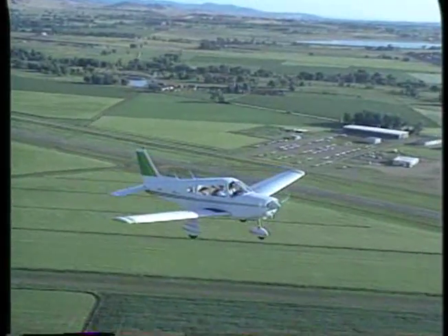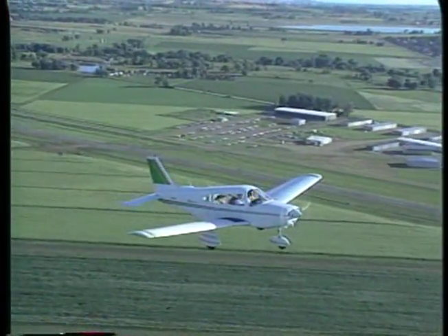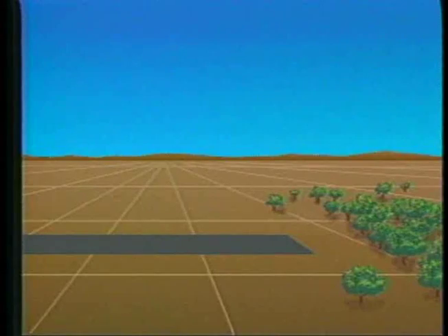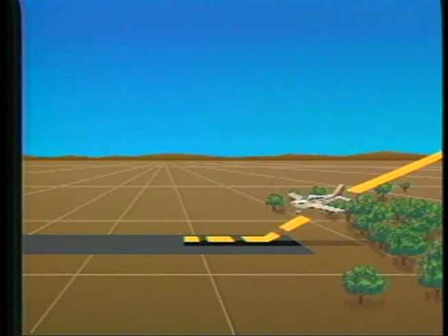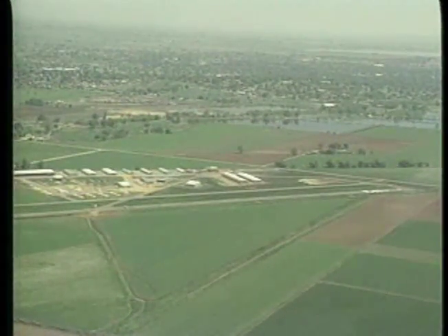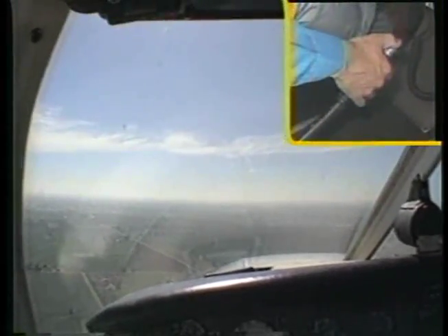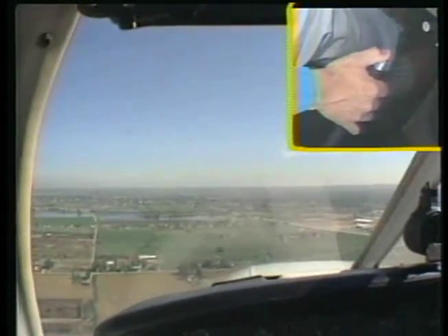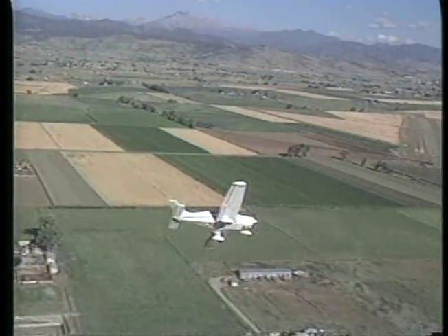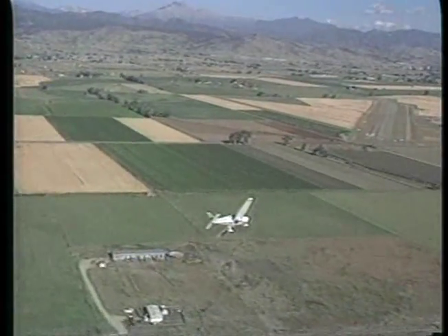You must also apply special techniques when landing on a short field. The objective is to touch down near the approach end in a full stall attitude. For training, you should assume that the approach is over a 50-foot obstacle. Your preparation for the landing begins on the downwind leg of the traffic pattern, where you slow the airplane to pattern speed and extend the flaps to the first position. Apply the remaining flaps as you continue through the base leg and after the turn to final.